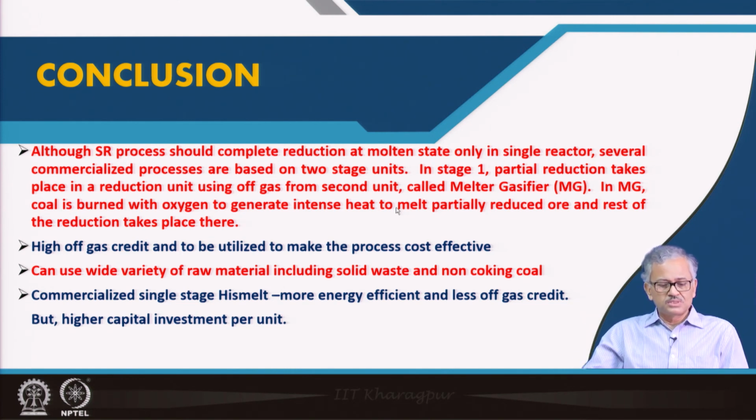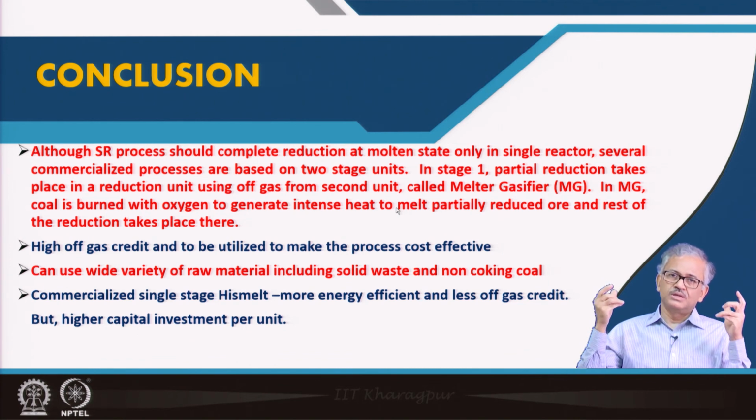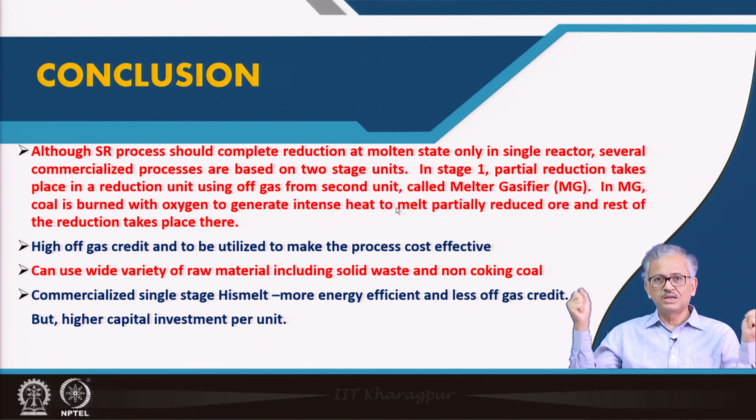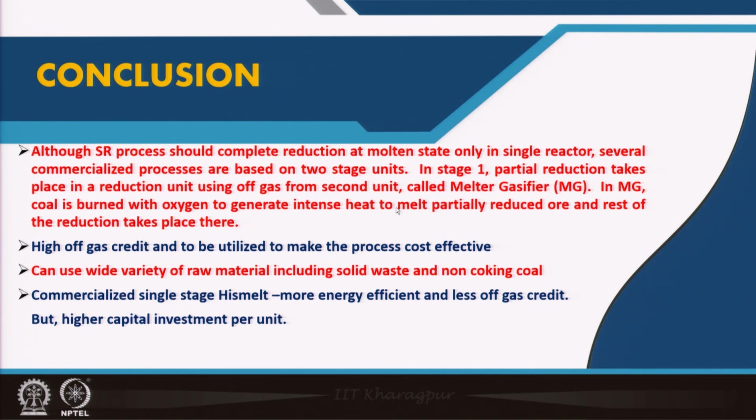But the most popularized processes are the Corex process as well as the Finex process. The Corex process is most popular, and it is basically a two-stage process, because if you want to use iron ore, lumpy ore or pellets, then the two-stage process is better. Or if I want to directly use the iron bearing waste, iron ore fines and all this, then a single stage process can go. Because in India we have iron ore deposits, we have the availability of lumpy ore, little low grade alkali iron ore lumpy ores. So in that case we can go for the Corex process, that's why the Corex process has come.